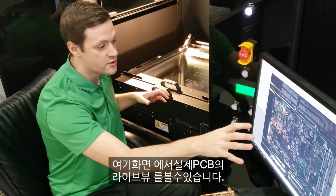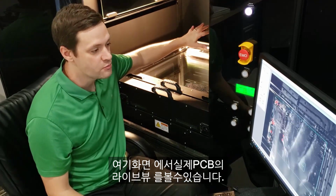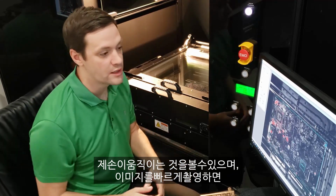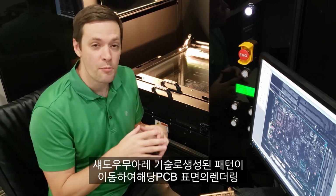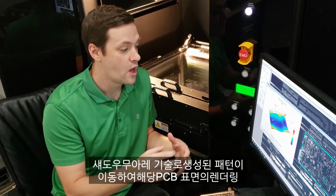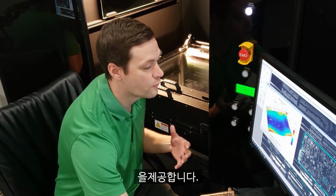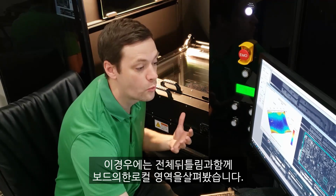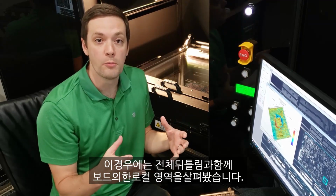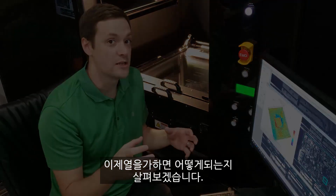So here on the screen, you will be able to see a live view of our actual PCB. You can see my hand moving there, and then if we quickly take an image, the patterns created by our shadow array technology are going to shift and give us a rendering of that PCB surface. In this case, I've taken the global warpage as well as looked at one local area on the board. All right, so we'll take a look at what this does as we heat it now.